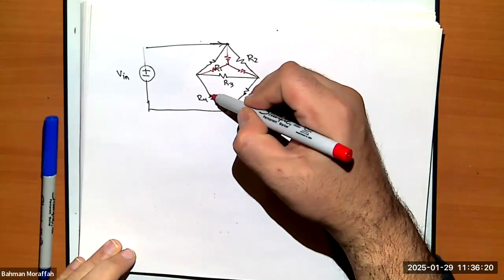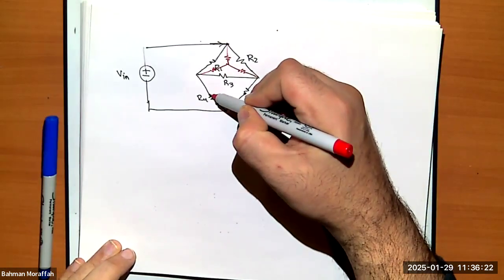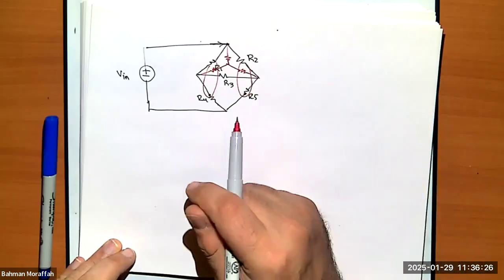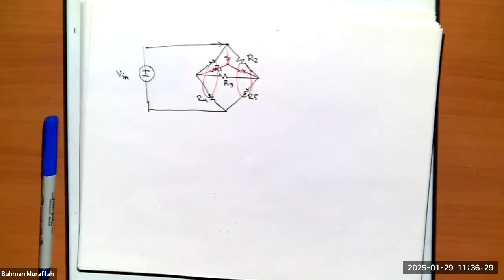This one and this one, they're in series. The result, these 2 and these 2, are in parallel, and then the whole thing is in series. So it would have been very nice if I could just replace that whole triangle thing with this upside down Y circuit.